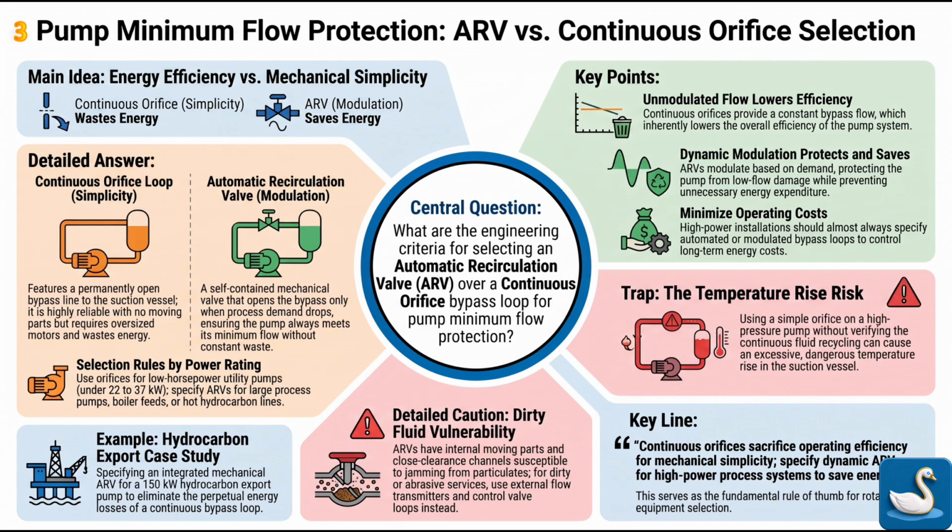When a pump generates massive high pressure, the motor imparts significant mechanical kinetic energy into the fluid. If that high-energy fluid is continuously recycled through a restricted orifice and dumped right back into the suction vessel, that kinetic energy experiences immense friction. Immense friction. It has nowhere to go. Therefore, the mechanical energy converts directly into thermal heat. And because it is a closed loop, that heat simply compounds.